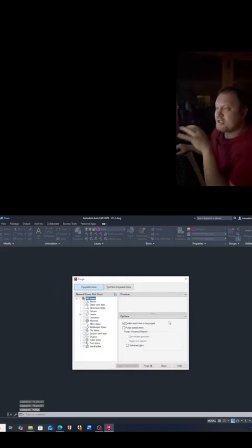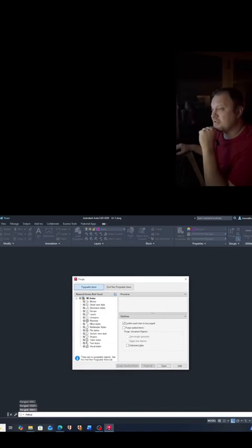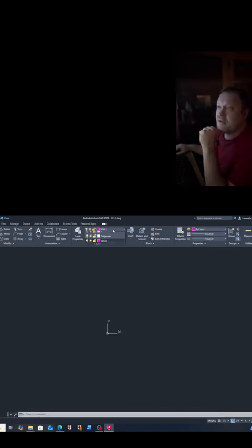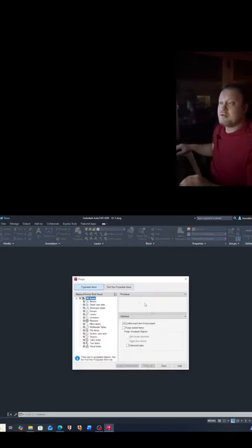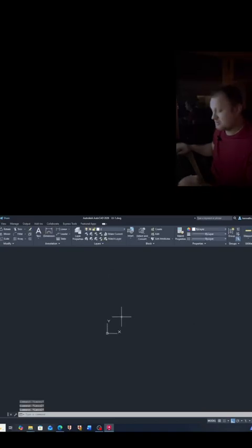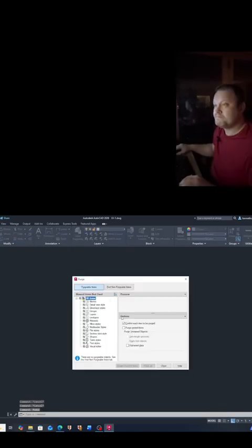So we're going to delete this, and then when you delete everything like this, then you want to purge. And then purging, you just type in purge, P-U-R-G-E, and we're going to select all items. So let's purge all checked items, and close now. I'm going to set this to 0 and purge one more time. Because wall was selected as the layer that I was using, it won't purge the current layer.